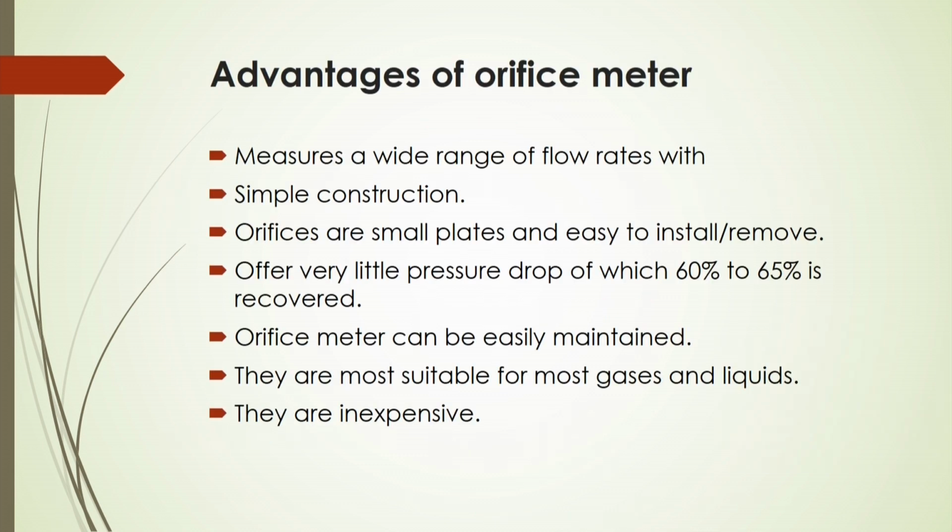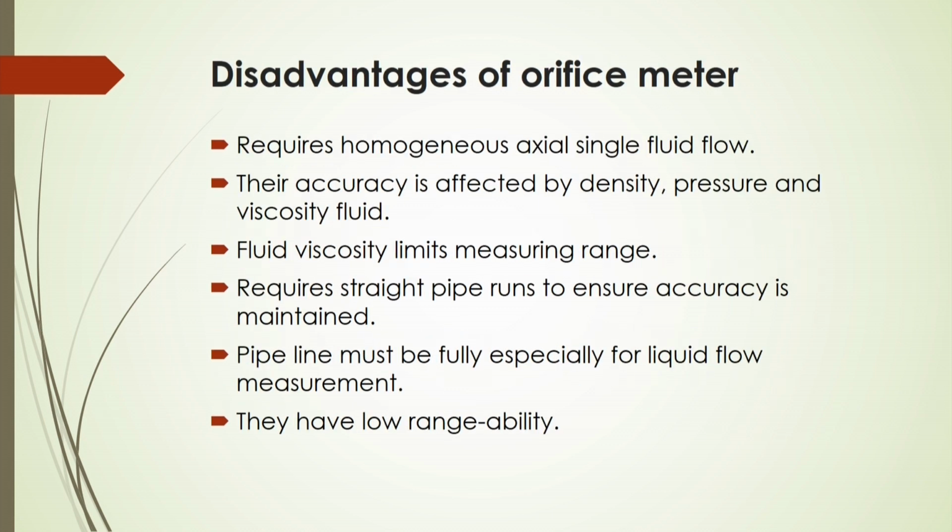What are the advantages of the orifice meter? This orifice meter measures a wide range of flow rates with simple construction. Orifices are small plates and easy to install or remove, offer very little pressure loss of which 60% to 65% is recovered, and the orifice meter can be easily maintained. They are suitable for most gases and liquids, and they are inexpensive.